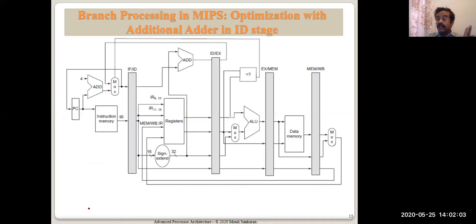Now it's an unconditional jump. There is no condition to check. So it will be immediately fed to the PC and a new PC will be found. Now, what is the gain you have in terms of stall? How many cycles is it going to waste now? Earlier, it wasted 2 cycles. It accessed PC plus 4 and PC plus 8. Then only the new address is fetched.